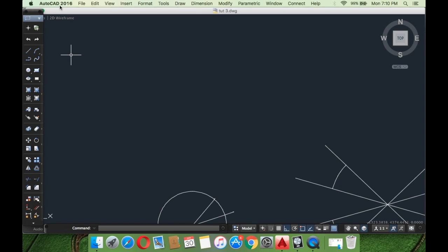So the next part that we come to is join. Now to join two points, suppose we have a simple rectangle. Suppose I'm dialing in 1000, then we go down, suppose it's half of it, 500, then we go this way again 1000, and then join it over here.